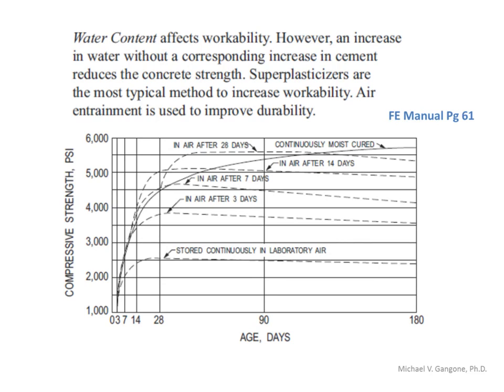Well, if you take a look, here's an example of a curve that you might see if you're curing something in open air. Suppose I'm not using burlap sacks, or I'm not using any plastic to keep that moisture in. Then what we see happening here is that the strength is not going to be able to fully gain.